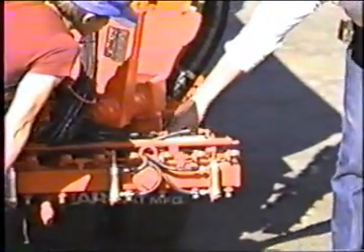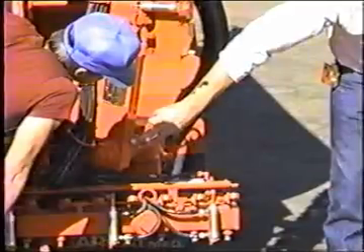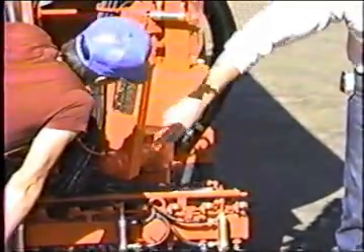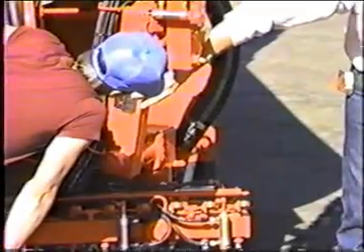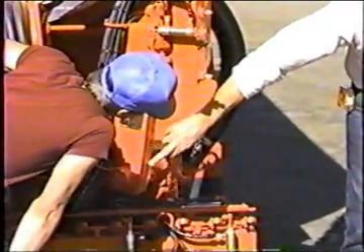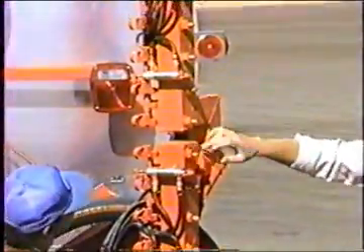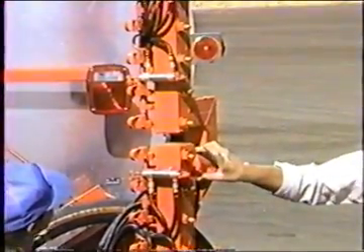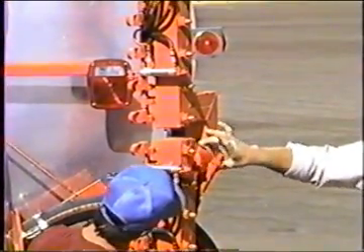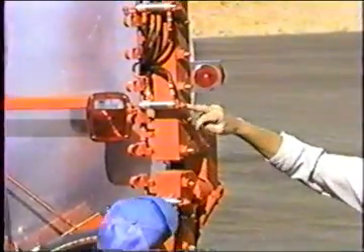That outer passage goes up. Outer passage goes to the rear. You can see that this feed tube is split. It's got a weld seam here. It has 2 passages all the way. The outer passage hooks us into the forward passage. That forward one goes up to here. Here it gets into the outer passage of this double swing joint. Outer passage, rear. Now we're into the valve section.